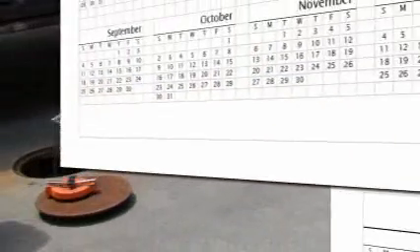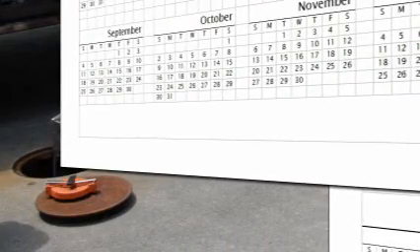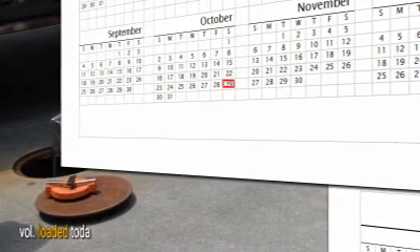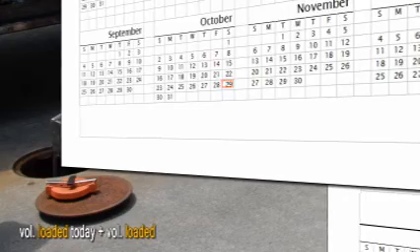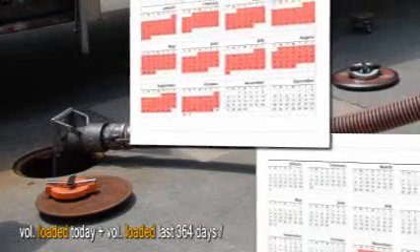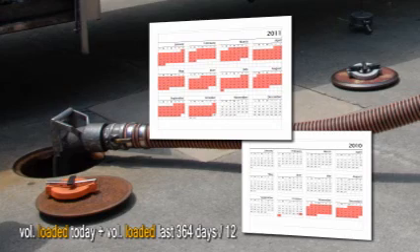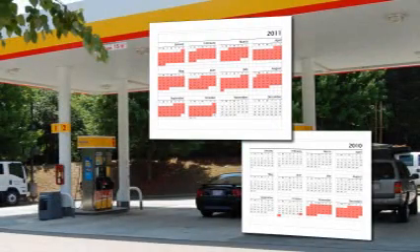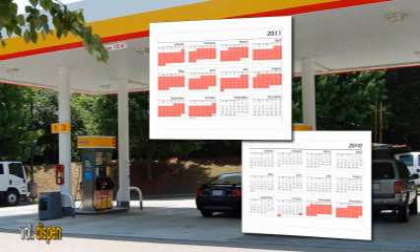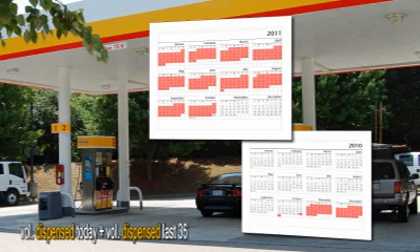Monthly throughput is calculated in one of 2 ways: the total amount of gasoline that is loaded during the current day, plus the total volume loaded during the previous 364 days divided by 12 months, or the total amount of gasoline that is dispensed from all gasoline storage tanks at the station during the current day, plus the total volume dispensed from all gasoline storage tanks during the previous 364 days divided by 12 months.